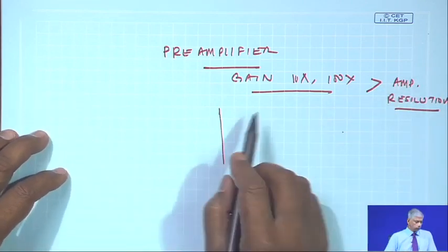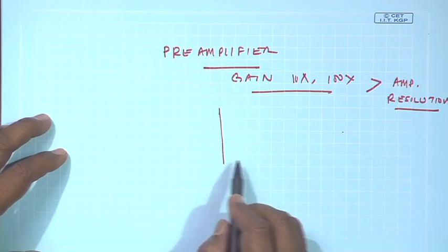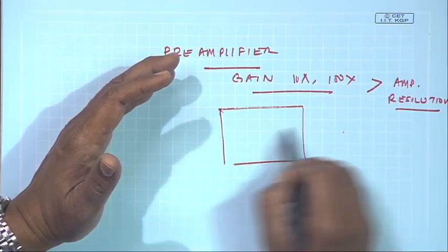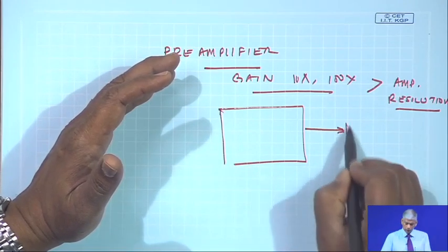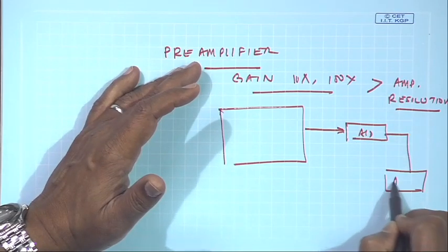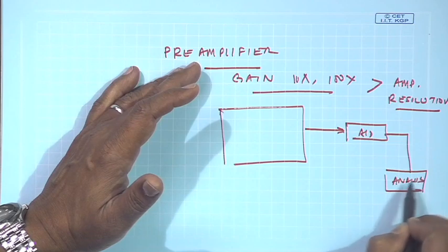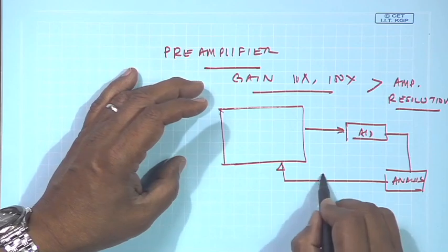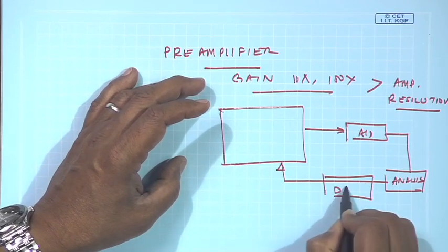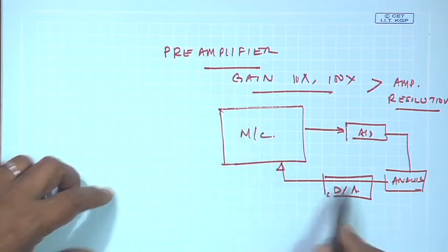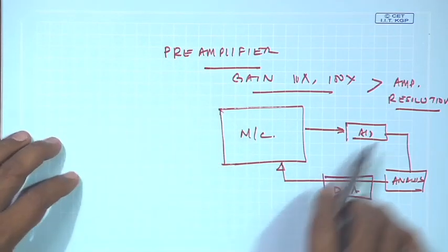Of course, nowadays this is an open loop process that we are doing in CBM, but there are many closed loop operations wherein after you take the signal through an A to D converter, you do an analysis and you want to control through a mechanical feedback on an actuator. So, we need what is known as digital to analog conversion. Some of the units have a D to A, and that is for closed loop control systems and so on.